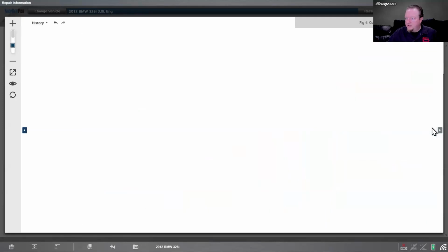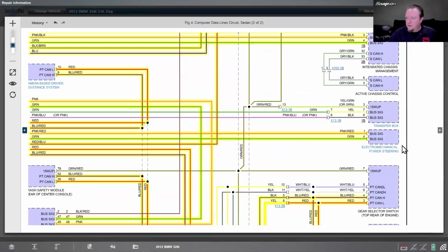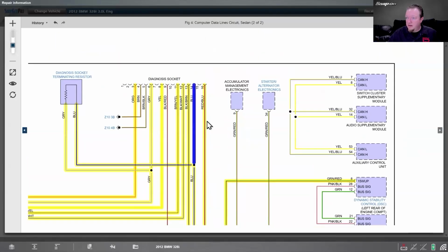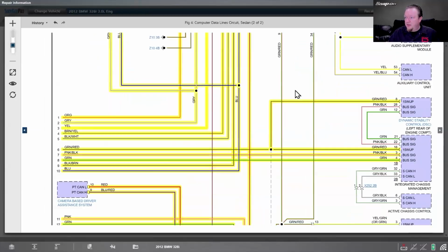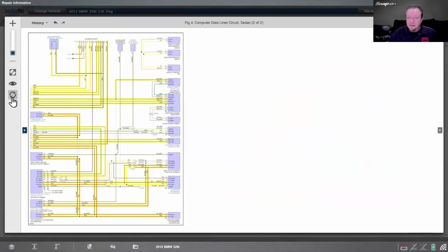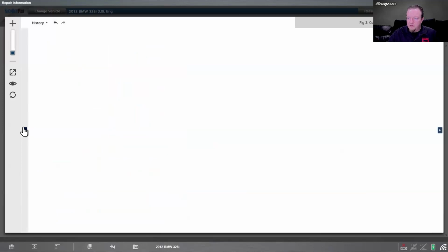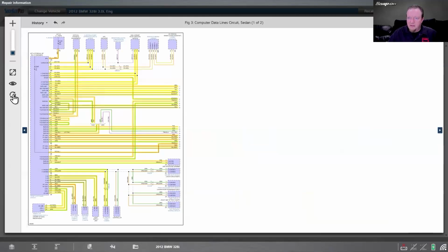And then if I go across the way, that's going to bring us to the, where is it? There it is, diagnostic connector right there at 16 pin. This one actually has a terminating resistor in there between 6 and 14 for the CAN bus. Interesting. You don't usually see that called out on many vehicles. This one also, if you notice, it has a couple splice connectors there, but it doesn't have any of those termination blocks that we looked at earlier. So this one's fairly straightforward.